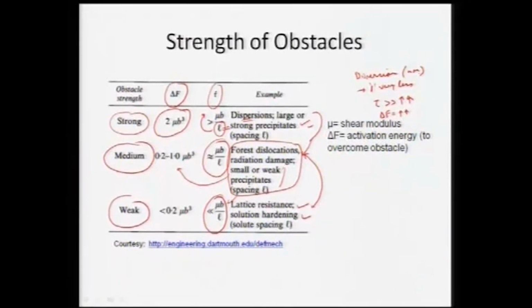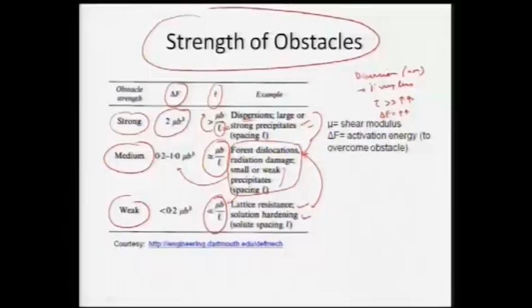In those terms we can reduce the creep of the material. Because we will have some creep, we have pinning agents such as very fine dispersants of ceramics present in a very soft matrix to resist the creep deformation in the material. That is how we can enhance the creep resistance of the material, by incorporating very fine ceramic particles to resist the deformation due to creep. And this obstacle strength can vary depending on what sort of obstacle is resisting the creep deformation.